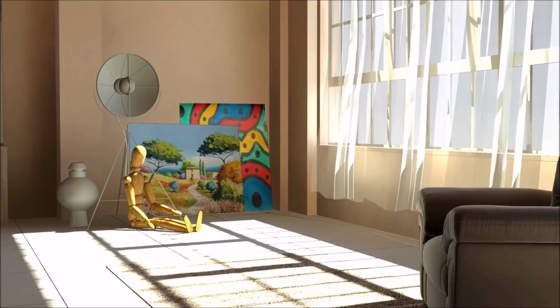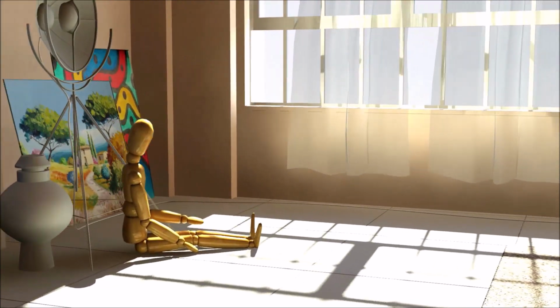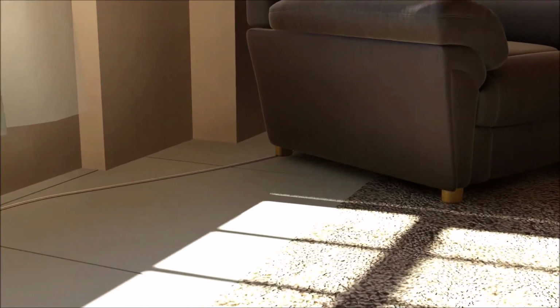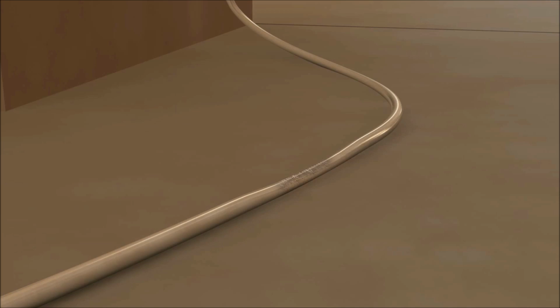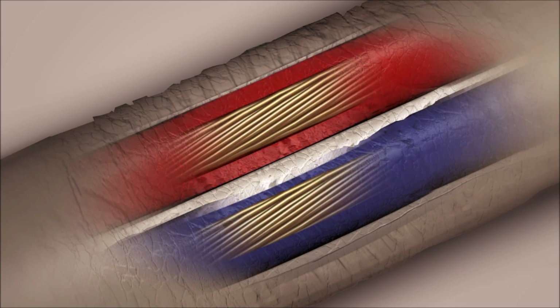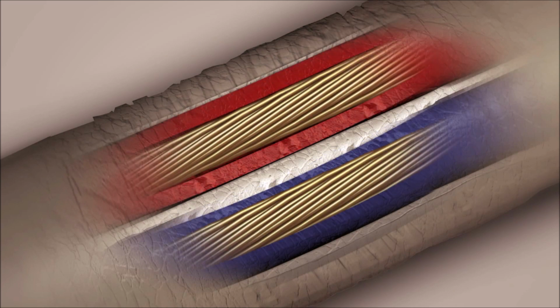An electrical fire can start without warning on any damaged electrical cable or connection in a home. Let's take a closer look at what happens when a cable's insulation is damaged. Damaged insulation lets current flow through, creating leakage current. To find the shortest path between two conductors, the leakage current produces electric arcs. Each arc makes a tiny burn in the insulation it passes through.